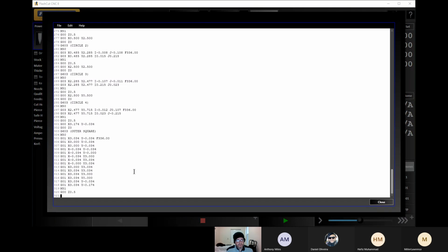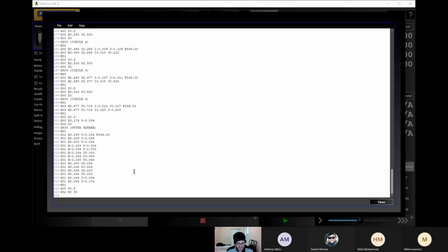We're in incremental programming now because we're using G52. We have to return it to absolute programming, okay? The way that we would do that is you put in G52, X0, Y0. That sends the virtual position back to our regular home position. And then you just add G00, X0, Y0.